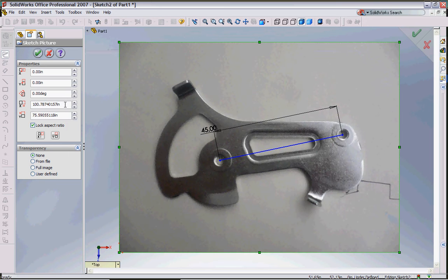So here on this dimension, first I measured in between these two holes, and this dimension right here when it's measured is 2.55, so we'll do times 2.55 divided by 45, so that's our scale factor. And then we'll click on enter, and it'll scale that down.